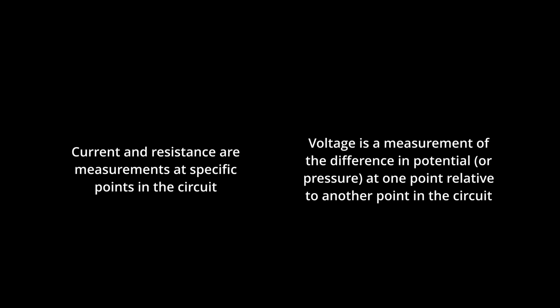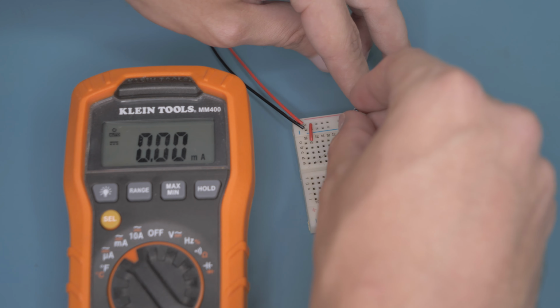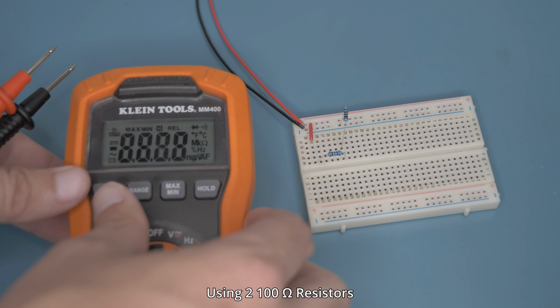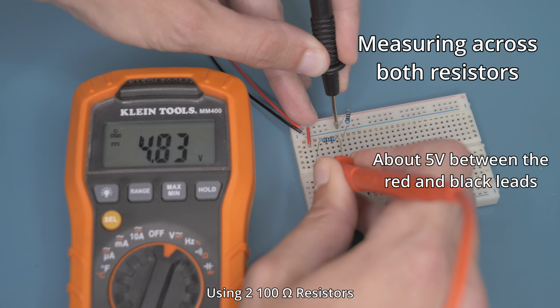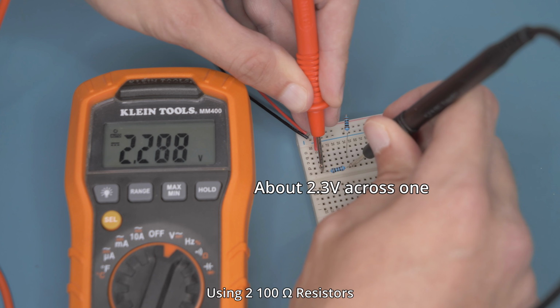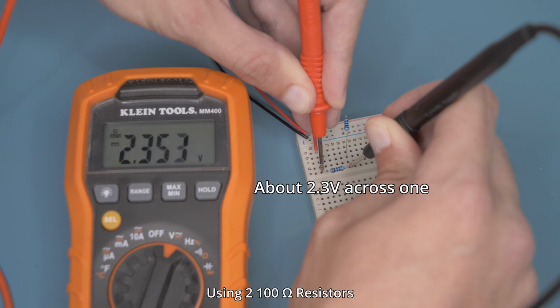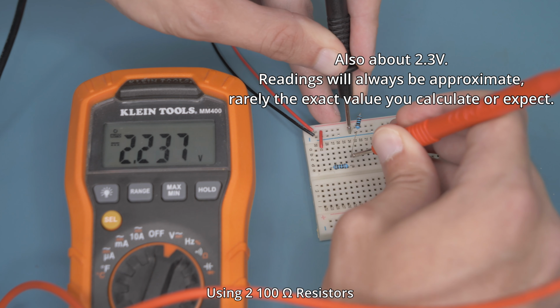It's not enough to simply say that a circuit has 5 volts of electrical pressure. You have to specify that it has 5 volts of pressure relative to another specific point in the circuit. When two resistors are in series like we have here, the voltage across both resistors will be equal to our supply voltage, which is 5 volts. However, the voltage will be divided between them, meaning if we measure across each resistor's leads individually, we'll get two different voltages that add up to 5 volts.